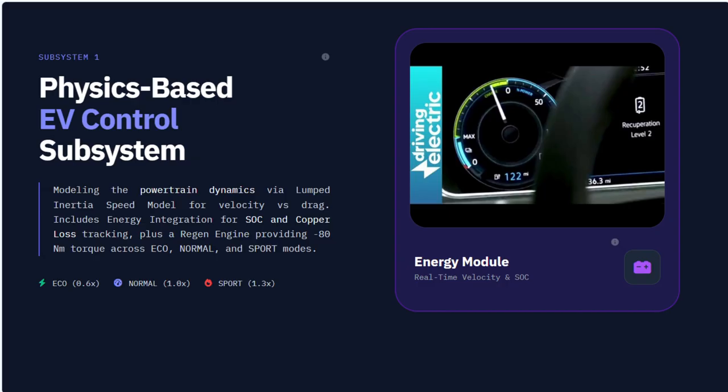Finally, we have an active regenerative braking engine, where a pedal difference across the 5% threshold makes the motor apply negative torque up to 18 newton-meters. This serves as the current flow to recapture kinetic energy and charge the simulated battery pack on the fly.